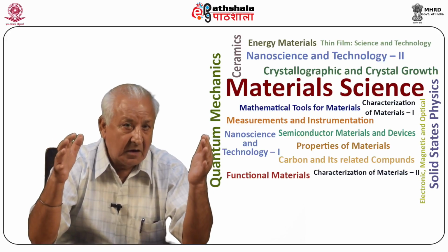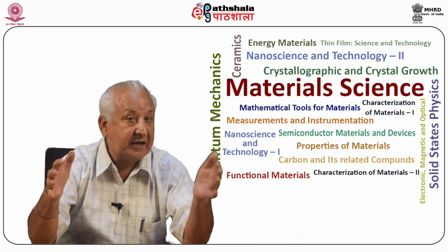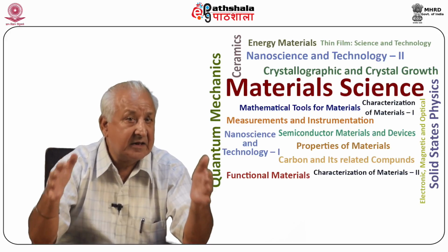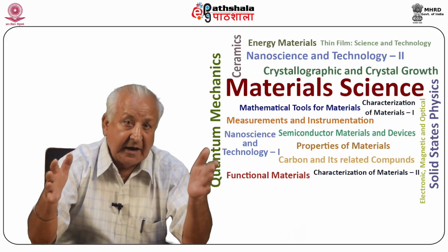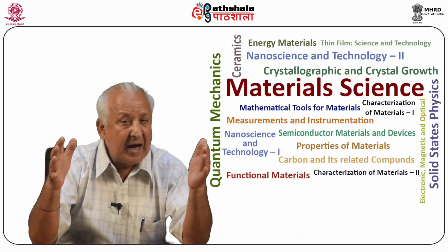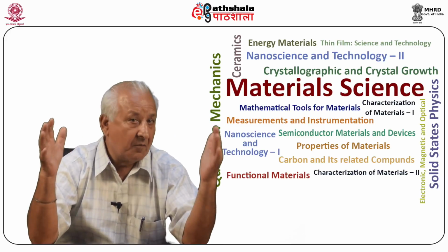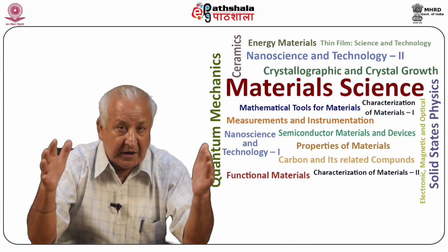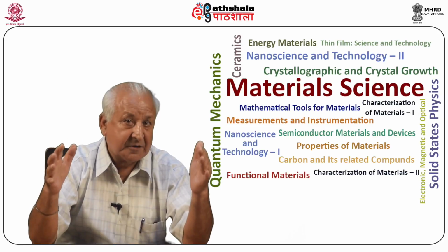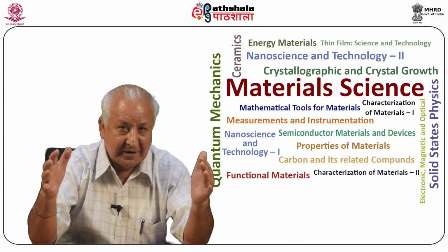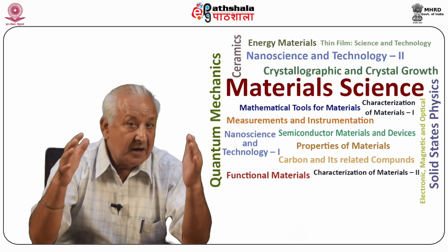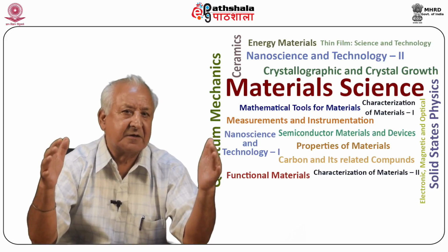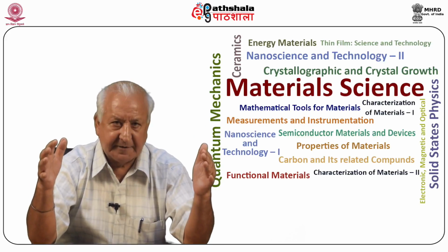Potassium dihydrogen phosphate, abbreviated as KDP, ammonium dihydrogen phosphate, abbreviated as ADP, optical grade sodium chloride crystals, and several others are grown from aqueous solutions. Quartz, of optical, electronic, and high Q value grade, is grown using the hydrothermal crystallization technique, whereas magnetic bubble domain materials and several useful oxide crystals are grown using the flux method.